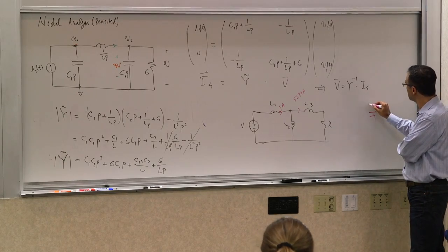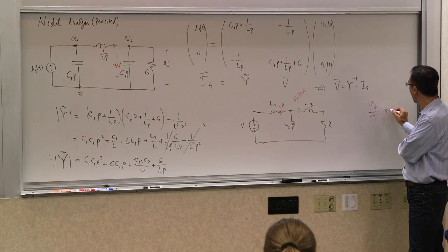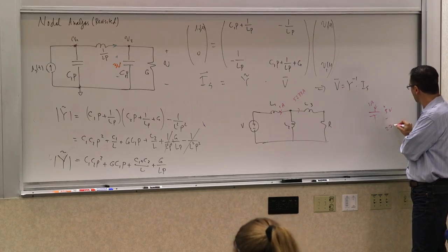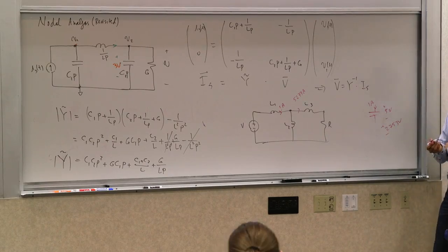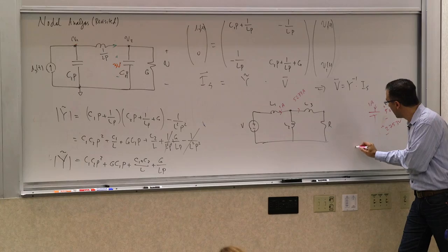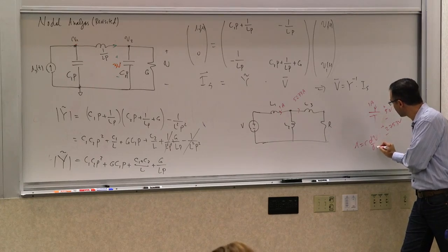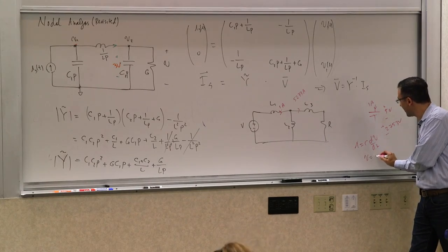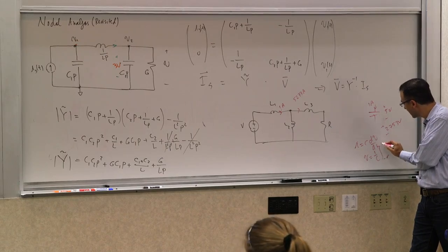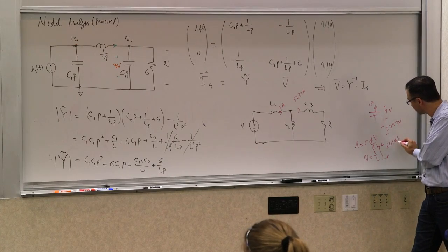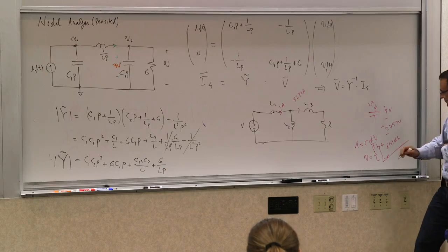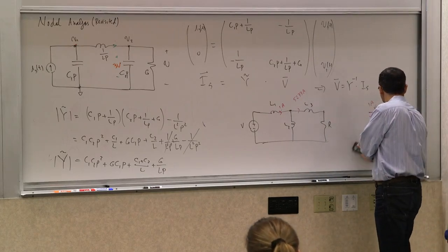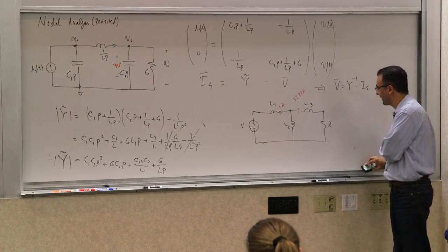If the current is 1 amp, this voltage at that instant could be 5 volts, it could be 2,753 volts, any arbitrary value, because I is C dV/dt, which means that V depends not only on the instantaneous value of the current, but also all of its past history. That's the memory part of it. Okay, so now let's go back to the question in hand.